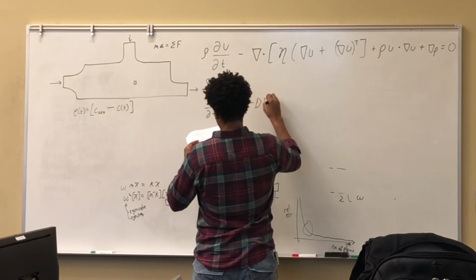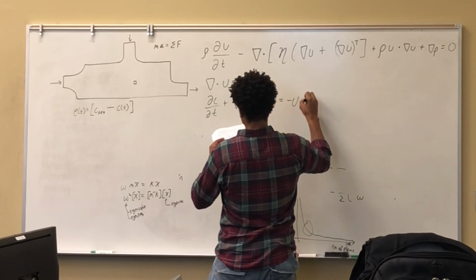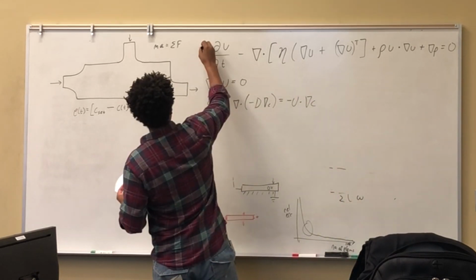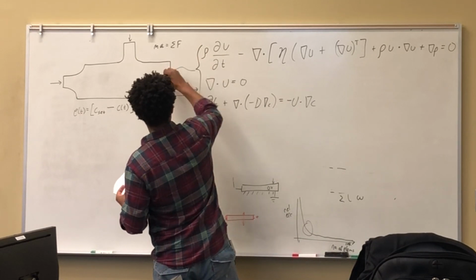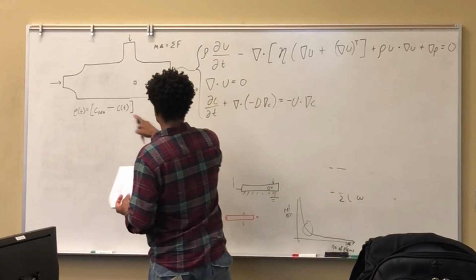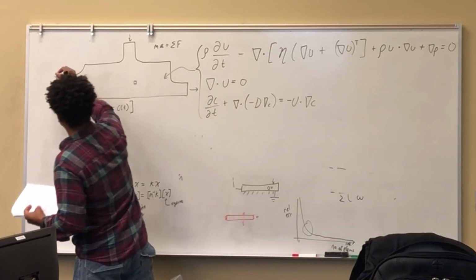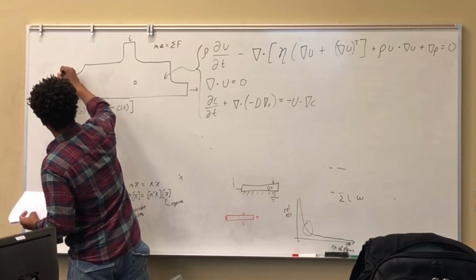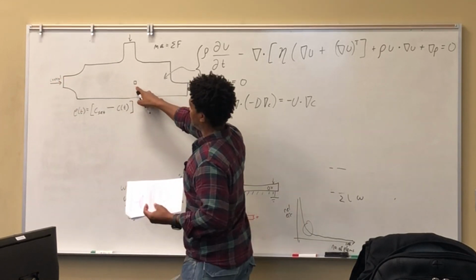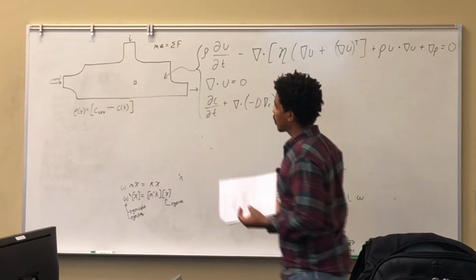Of course, COMSOL is going to supply this for you, and this is simulating the physics all inside there. Now what we're going to do is have this PID controller to try to adjust this input, so this is the control input right here. This input is constant. We're going to adjust this input such that we achieve a certain concentration that's equal to this, and we want to try to achieve it as quickly as possible.